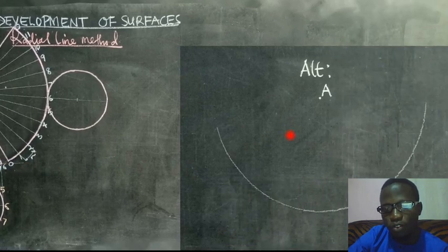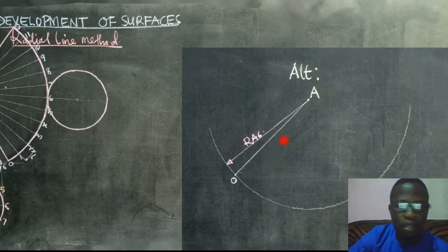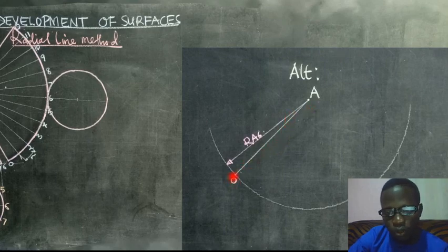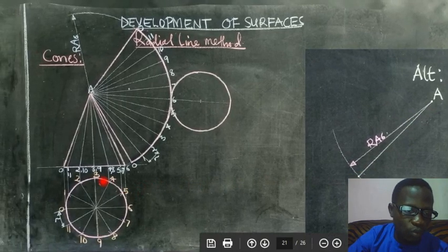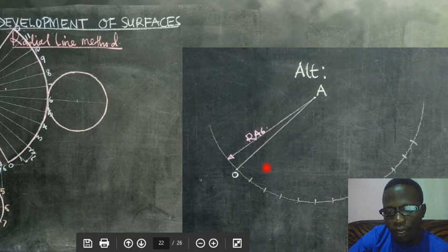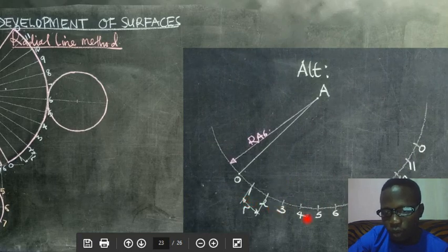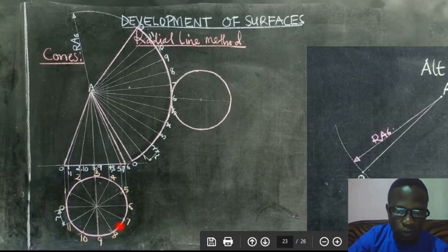Having drawn that, you can see I've demonstrated here that the radius is equal to r(6). Now we are going to create our divisions. We put the starting point, I've put 0, and we come to our base of the circle here. We take the small arc radius, we start marking off divisions until they reach 12, and we can label them as 0, 1, 2, 3, 4 up to 12, and the small arc radius is equivalent to the arc radius on the plan.